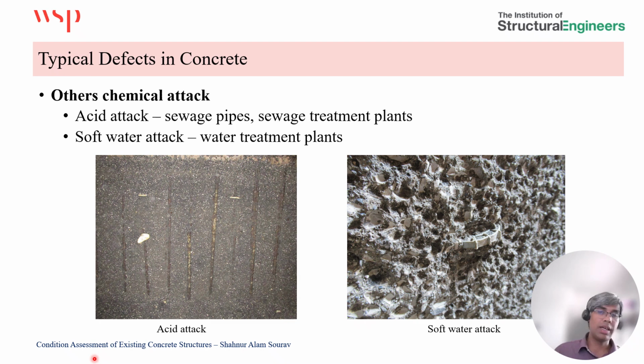As you can see in this photo on the left, all the reinforcement is already exposed due to the loss of cover concrete from acid attack. You can also see similar processes in the soft water attack, where all the aggregate has spalled from the cementitious matrix.